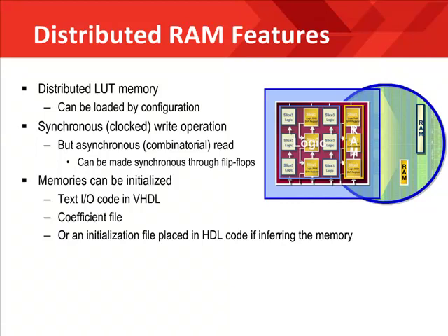The two LUTs in a slice, as well as the LUTs in other slices, can be used together to form a larger memory, but this will require extra logic for the input decode logic and the output multiplexer logic to do so. The caveat to this is that the memory built will not be as fast as one built with a block RAM, so most designers will opt for a block RAM implementation.